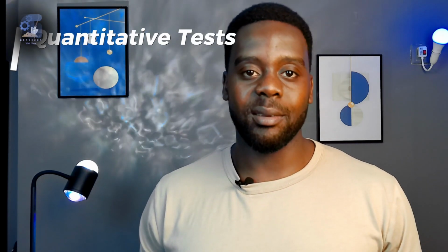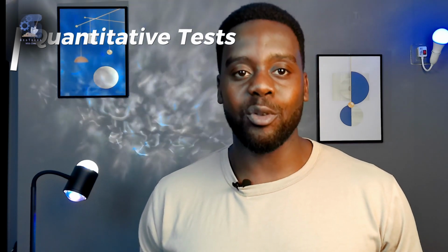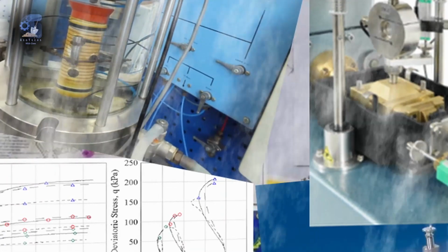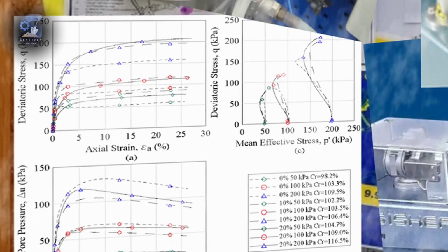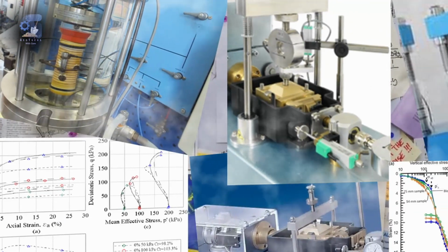The second class involves quantitative testing, which includes the measurement of the strength or compressibility of soil. For example, the triaxial compression test, the direct shear test, oedometer or consolidation test, and the measurement of chemical properties of the soil and the groundwater.